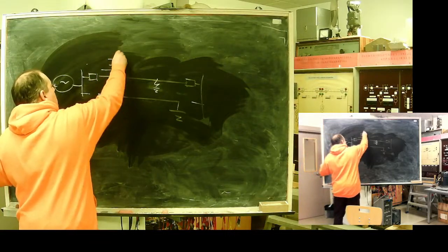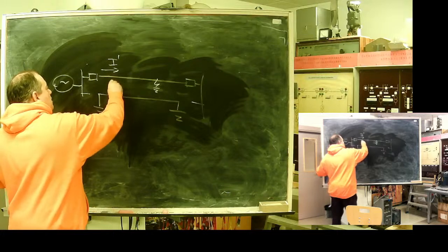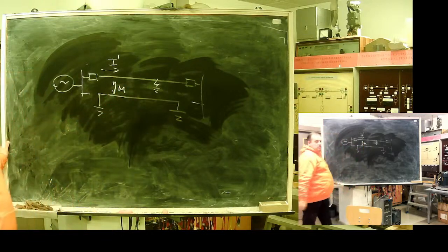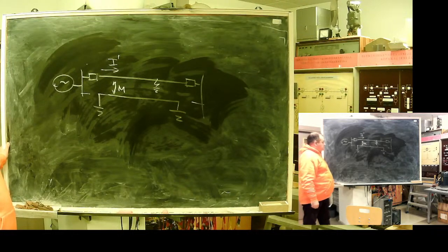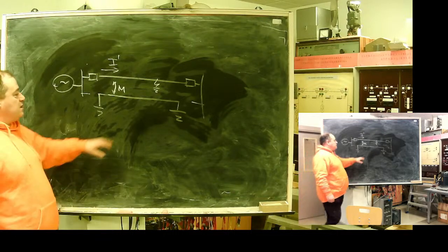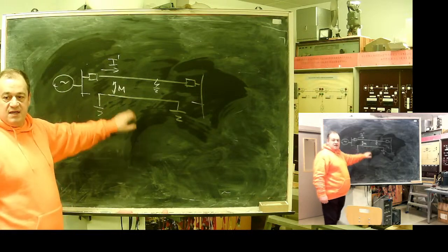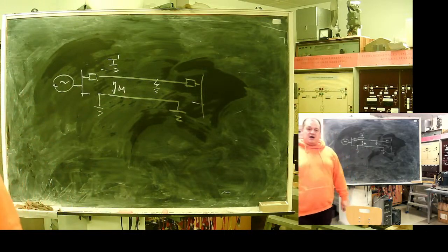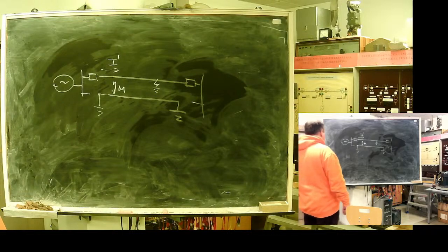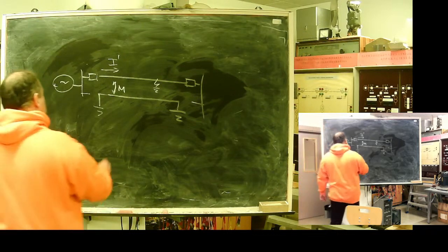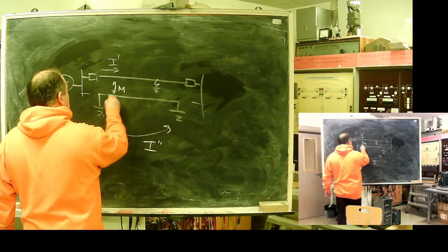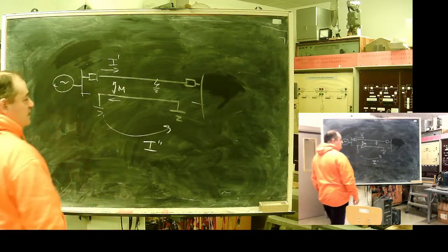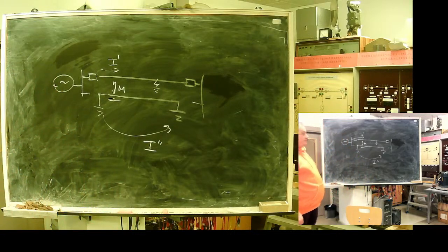We have our current. Because lines are coupled with mutual inductance, we will see circulating current in the disconnected line. It appears like some kind of black magic, but you will see current circulating here in the disconnected and earthed on both sides line.